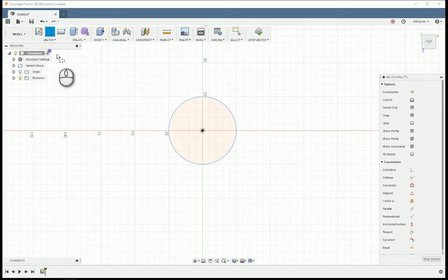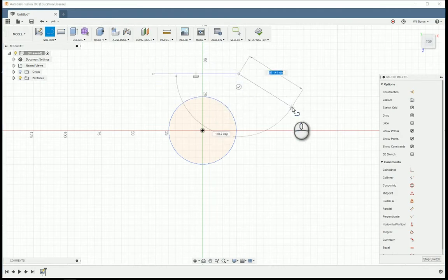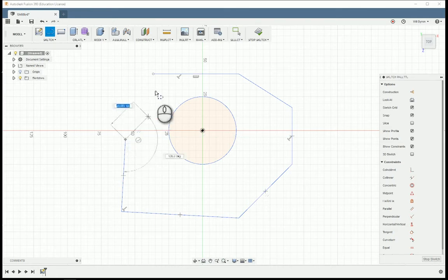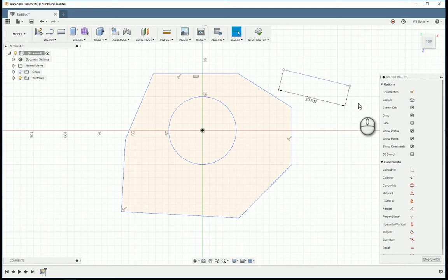So line specifically is you can draw as many straight lines as you want. Whenever you want to finish, you either need to click the check mark, or click on another point to finish. If you just hit enter, it'll stop wherever you are. So just hitting enter will only make a line that long.